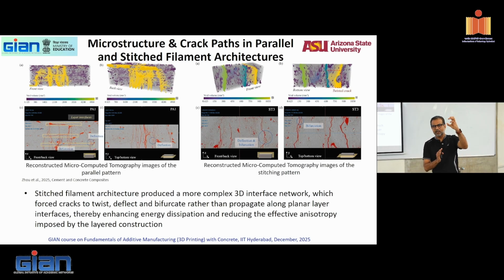As the crack needs energy to come through, you can put a hole in the front. How many of you have done some basic fracture mechanics class? All of you know the idea of stress concentration of a hole. The idea that you drill a hole in front of a coming crack is simply that the crack loses steam. The crack is confused as to what to do at that point of time. You reduce the stress concentration factor at that area. So all of these techniques you can bring together and create crack deflection, crack bifurcation.